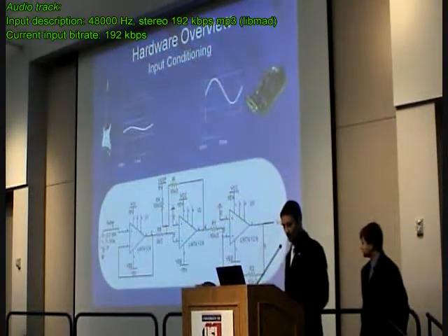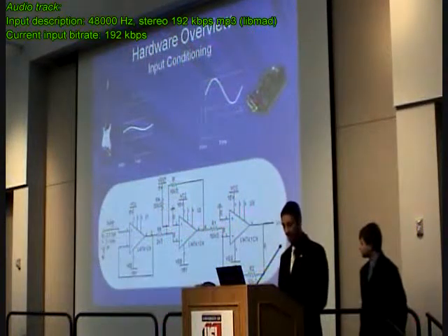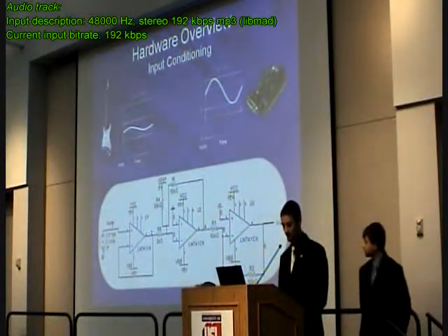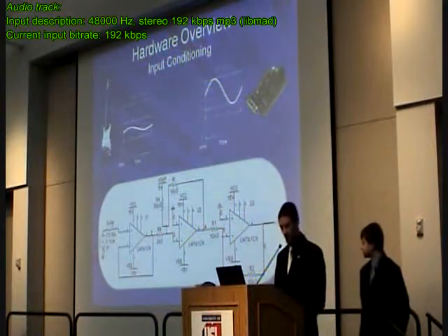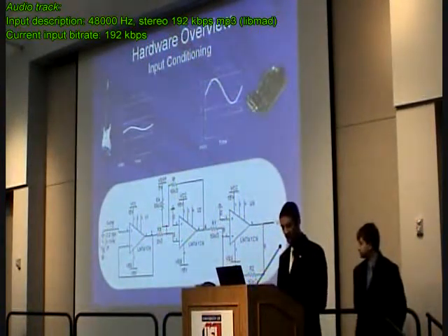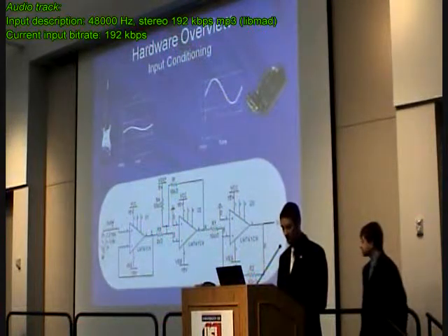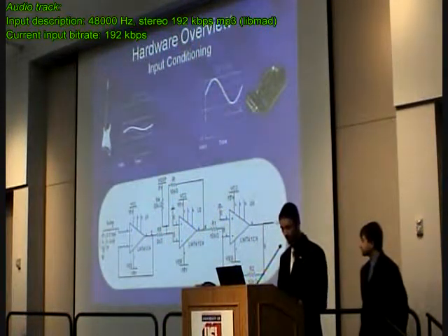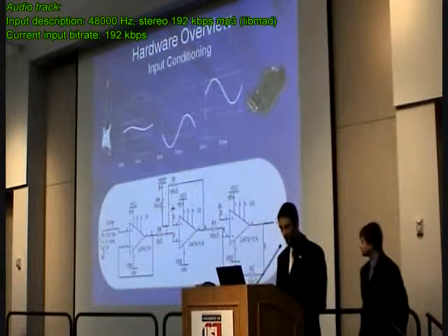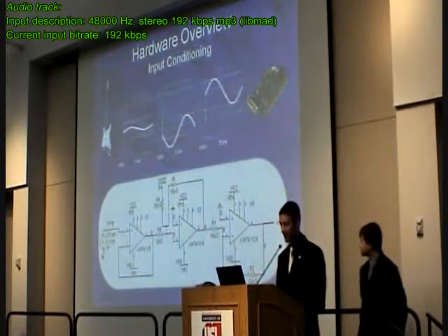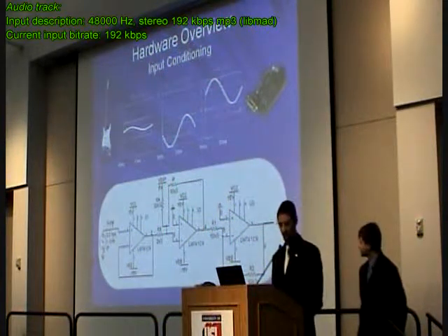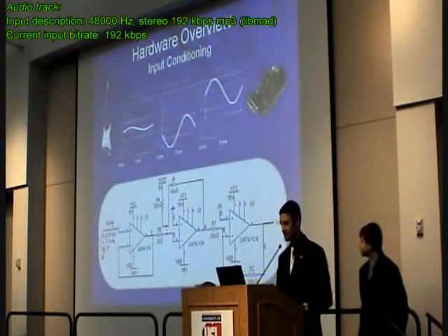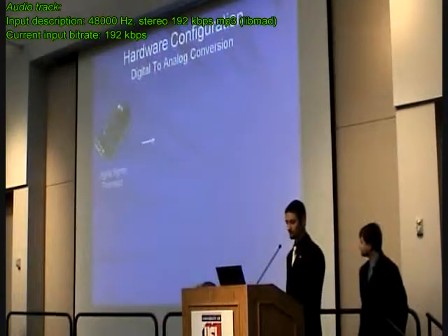The 3 op-amps are combined in the schematic below to shift and scale this input signal. The first op-amp buffers the signal by electrically isolating it from the guitar and the rest of the system. The second op-amp is configured as a summing amplifier, which scales and shifts the signal into a 3-volt range. However, this type of configuration places the signal into the negative range. So an inverting amplifier, the third one, is used to reflect the signal back into the positive region.